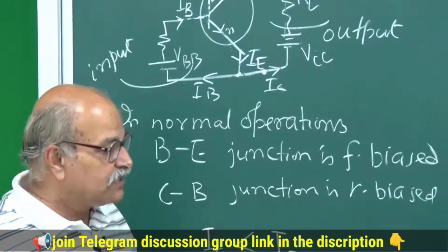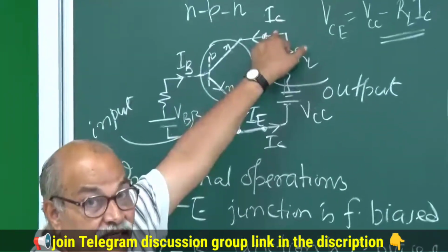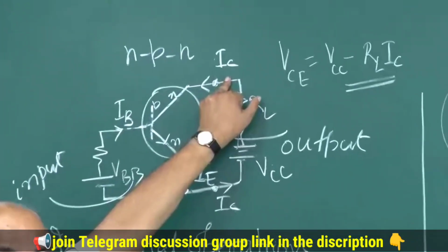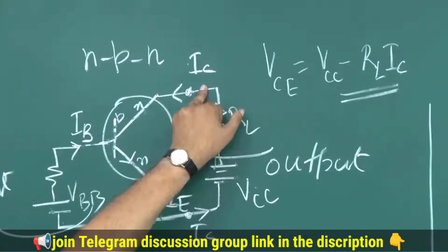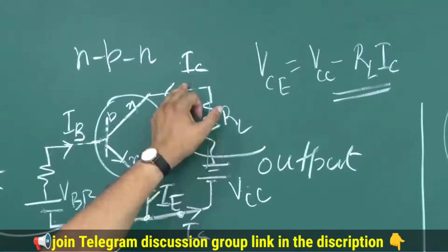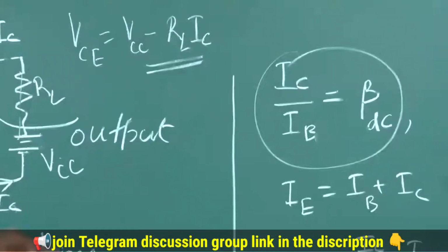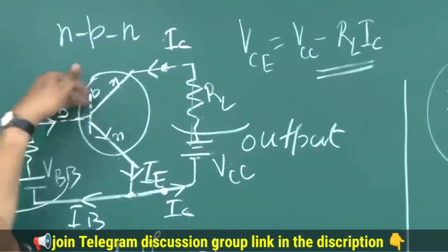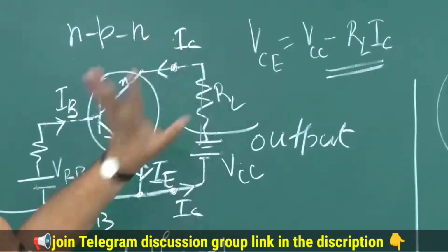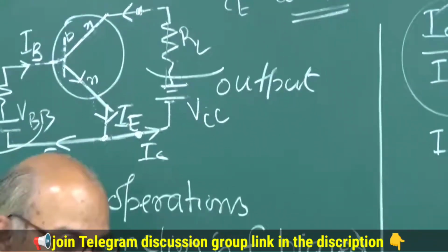And then we have the saturation region, where current is there, the transistor is active, but the capability of drawing more electrons at the collector is saturated. In that case, IC will be smaller than beta times IB, and if you increase IB, the collector is not ready to respond. So you have some kind of constant current after that. These are the regions.